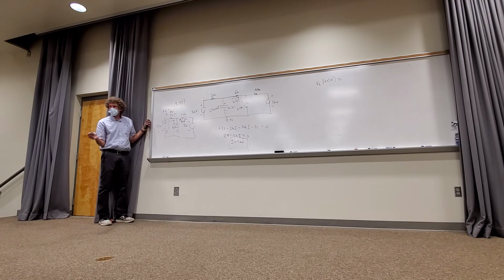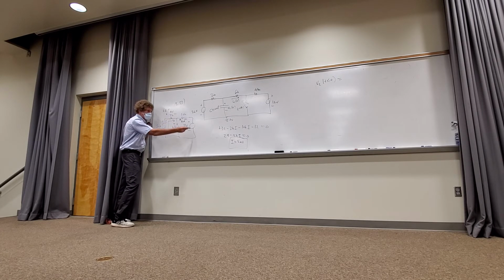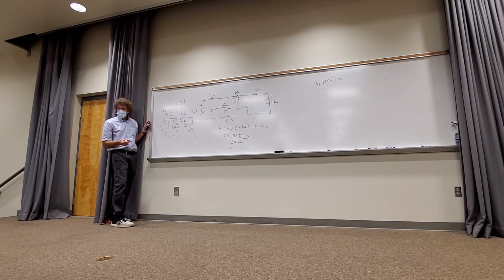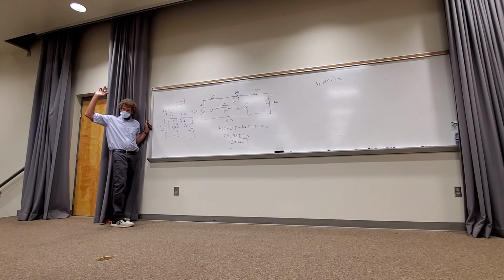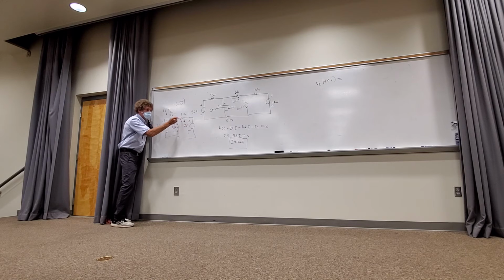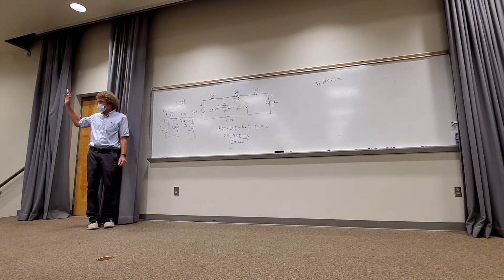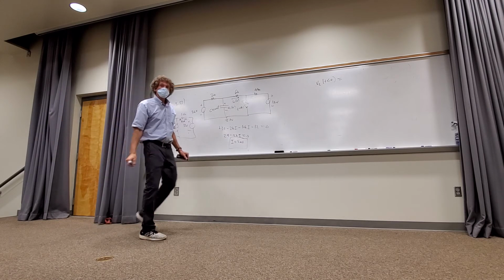Now, I need to get the voltage between the negative and positive terminals. The way I've mentioned over and over, start the negative and work back to the positive. You can go that way or you can go this way. You all see that? How many see it's 32 volts? Prove it to yourself. Start the negative, increase to 12, increase to 20, 32, correct? Go this way, increase to 36, loss of 4, 32. Correct, class? Okay. So we know this is 32 volts.